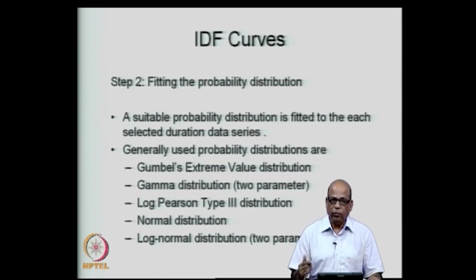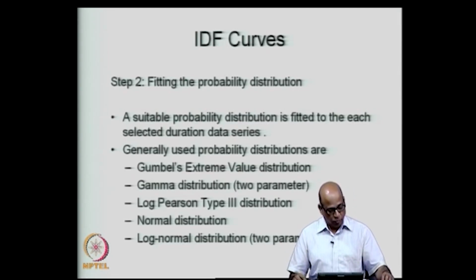And then we have to satisfy ourselves that the distribution that we are using is in fact a good fit for the data that we have. So, for 1 hour duration you may come up with one distribution, for 2 hours you may come up with another, 24 hours yet another, and so on. Corresponding to each of these series you identify the distribution that fits that particular data series best, and then use that distribution to do the further analysis.